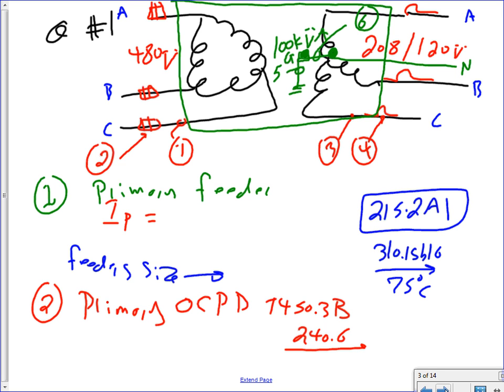They're all 3-phase. Everything is 3-phase. You see phase A, phase B, phase C, and A, B, C. Cool. Can I have thumbs up? We understand what type of transformer we're dealing with here? We're dealing with 480 on one side, 208/120. Where would I use a transformer like this? To feed a receptacle panel from a 480 system. You're going to be doing it not in this project, next project. If you get it now, you're good to go. If you didn't get it now, you have another chance next project.